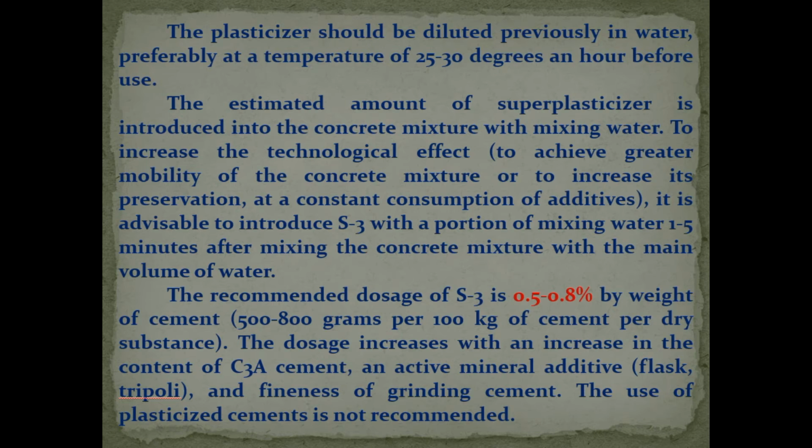It is advisable to introduce SP with a portion of mixing water 5 minutes after mixing the concrete mixture with the main volume of water. The recommended dosage of SP is 0.5 to 0.8% by weight of cement, 500 to 800 grams per 100 kilograms of cement per dry substance.